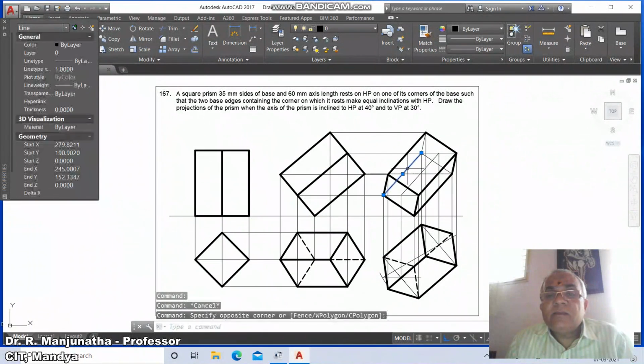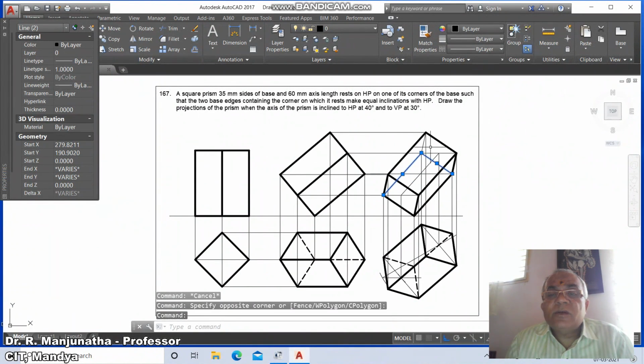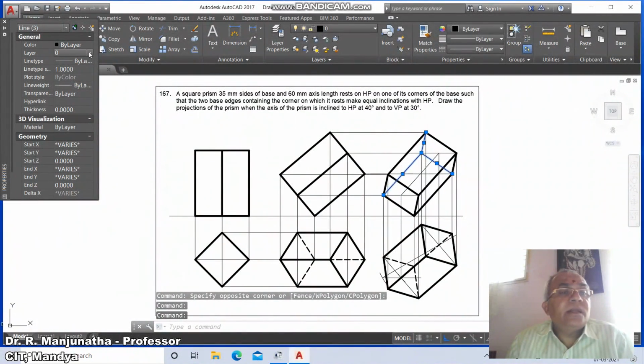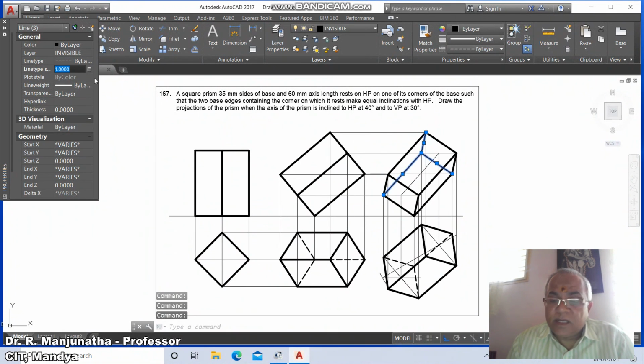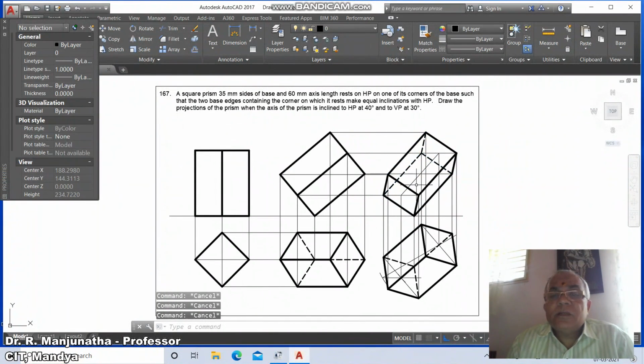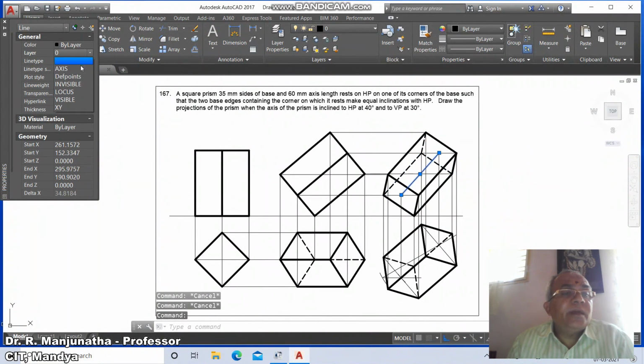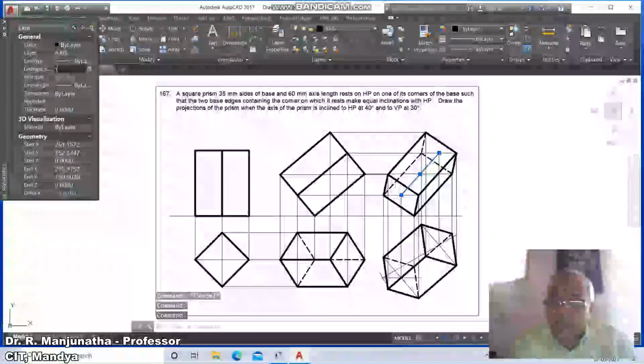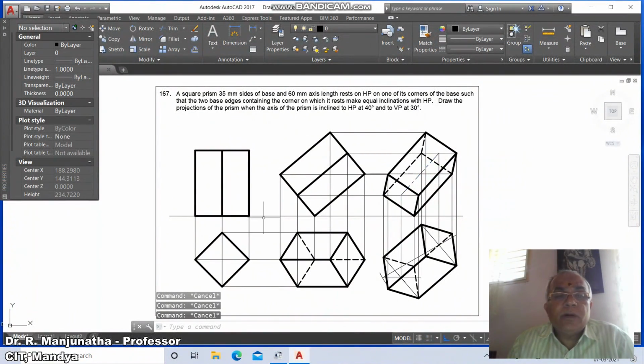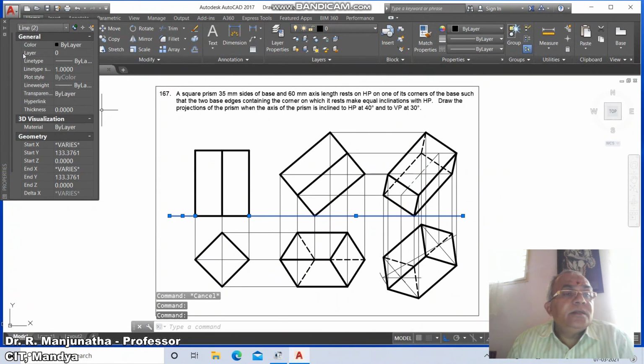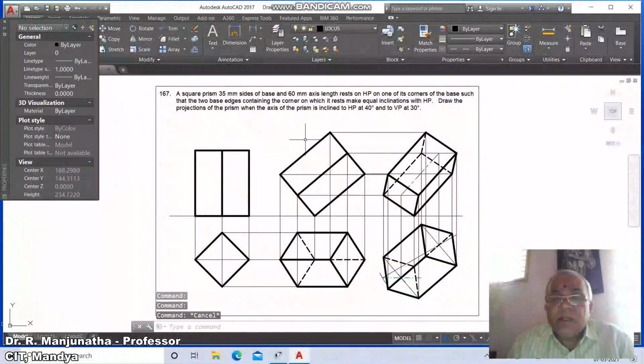Then you select this line which is crossing this, select again this line which is crossing. So since these two lines are invisible, naturally this line also becomes invisible, and take the distance as 10 and you make this distance as 20. Then you just click on this and go to layer, take this name as axis and take the distance as 10. Once you do that, you come down to this line and you come down to this line, change this layer to XY line. Then similarly you select this line and go to layer, make this as locus, change this dimension as 10, line type scale factor.